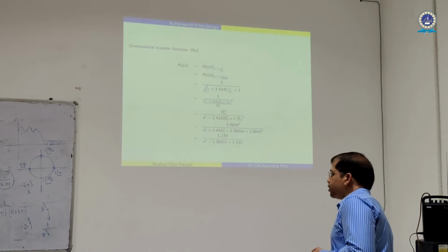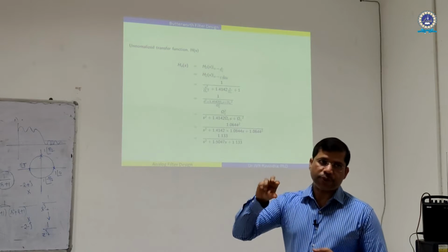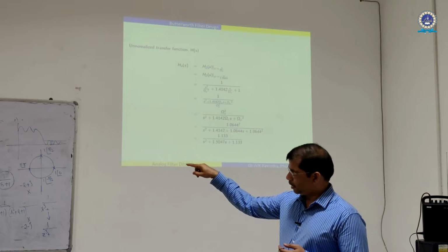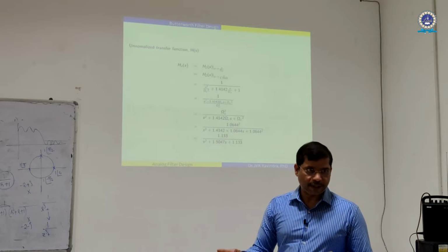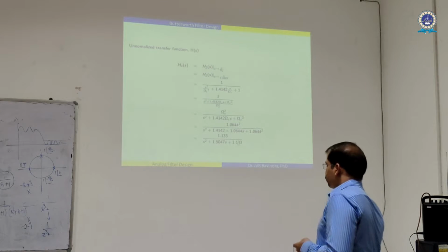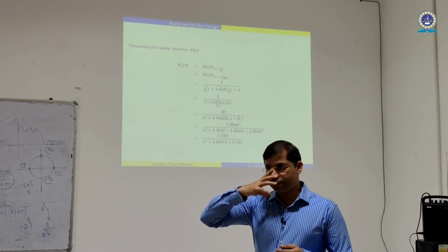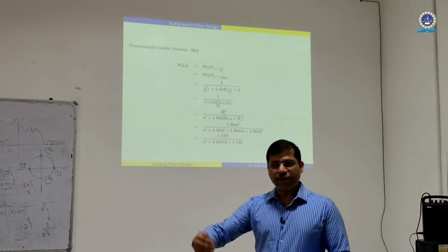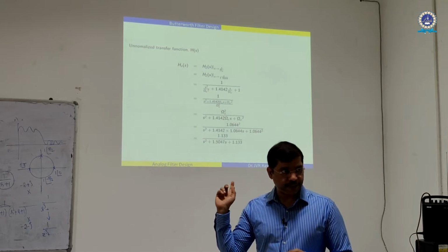So this transfer function is the appropriate transfer function for the values that you have chosen. Otherwise, irrespective of the graph, you will land on only 1 by s square plus root 2s plus 1, which is not correct. So that's the reason this transformation is right. Now you have to stop here, move to control systems, and look at the location of all the poles. If you feel that it is stable, then we move further. So stability conditions should be checked thoroughly at this point.